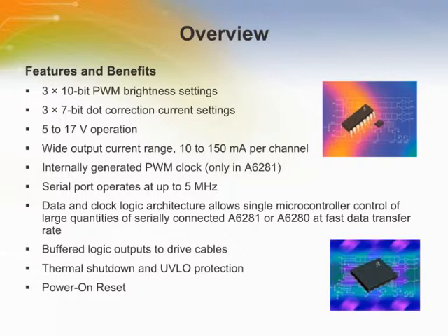It precisely controls LED brightness via 10-bit pulse width modulation per channel, complemented by 7 bits analog current control per channel to adjust color balance. The LED drivers are designed to minimize the number of components needed to drive LEDs with large pixel spacing.